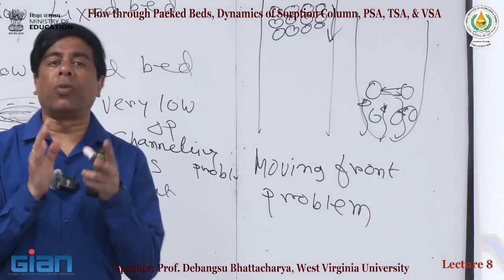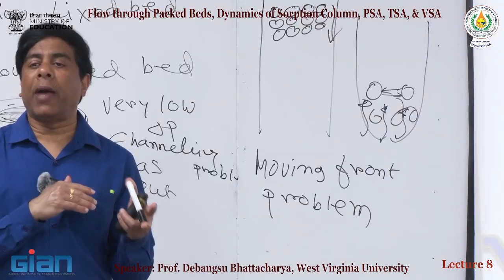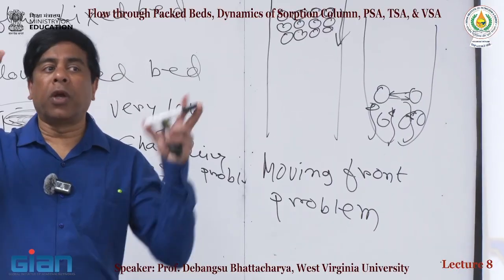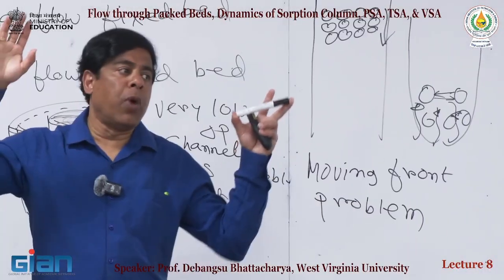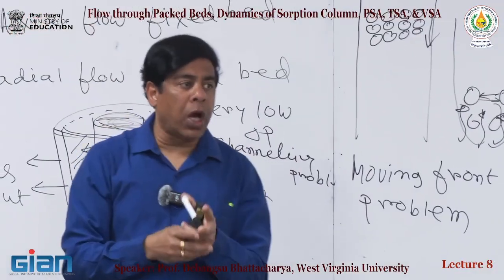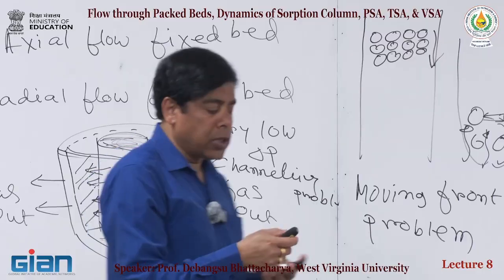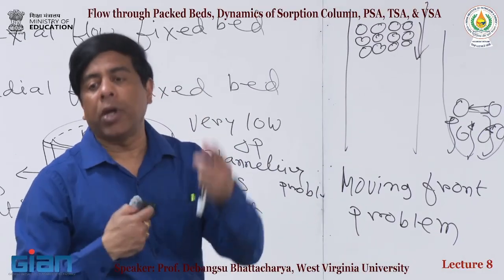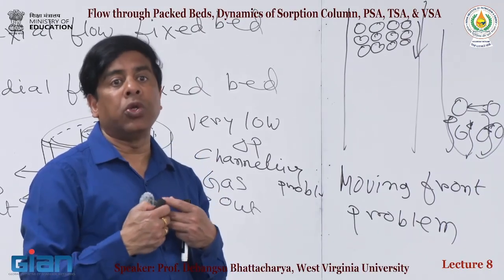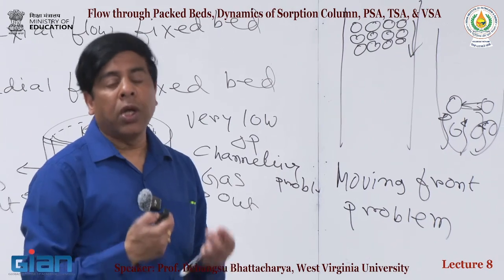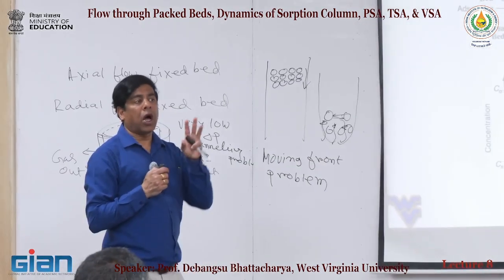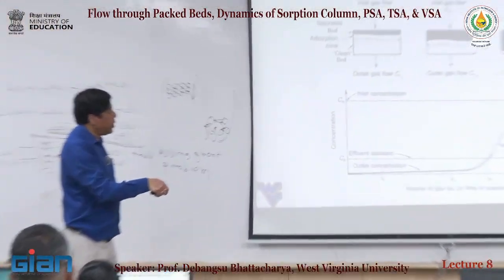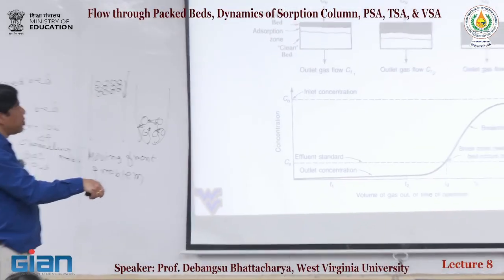So if you are observing or measuring this at the lab scale and you do a breakthrough curve, this can be pretty confusing because you have no idea what is happening. Suddenly it shows up, but at that point it does not give you a very clear indication of what has happened in the bed. That is why we really need to do the simulation, because that will tell you how much of the bed is actually getting utilized here.